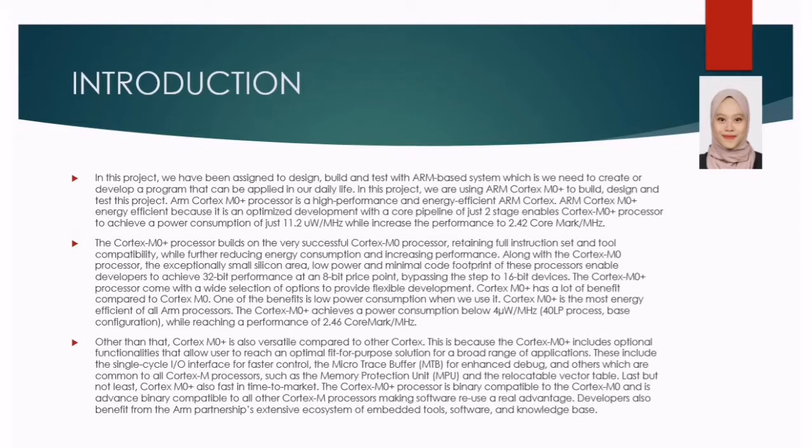Other than that, Cortex-M0+ is also versatile compared to other Cortex. This is because the Cortex-M0+ includes optional functionalities that allow users to reach an optimal fit-for-purpose solution for a broad range of applications. These include the single-cycle input or output interface for faster control, the micro trace buffer for enhanced debug, and others which are common to all Cortex-M processors, such as the memory protection unit MPU and the relocatable vector table. Last but not least, Cortex-M0+ is also fast in time to market.